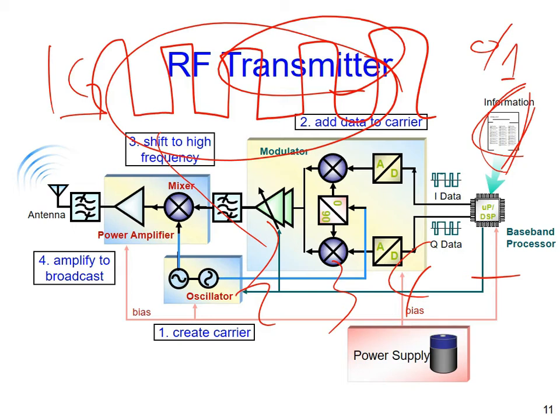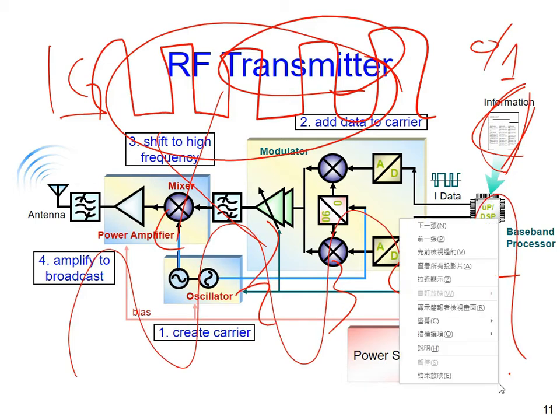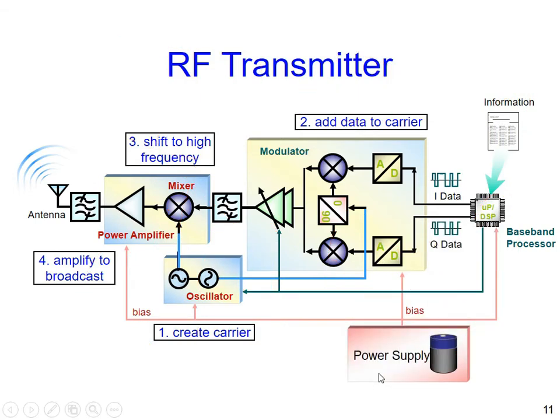Alright, so anything you would like to transmit wirelessly should look like this, a sine wave, a very pure sine wave. Okay. Only with a sine wave can you have the so-called single spectrum line. Okay, only one line in theory. But you need to do modulation because you don't transmit the pure sine wave to the other side. If so, the receiver can generate the sine wave by themselves, right? They don't need your help. So the information is modulated onto such kind of carrier, the sine wave, with phase modulation, magnitude, anyway, okay?